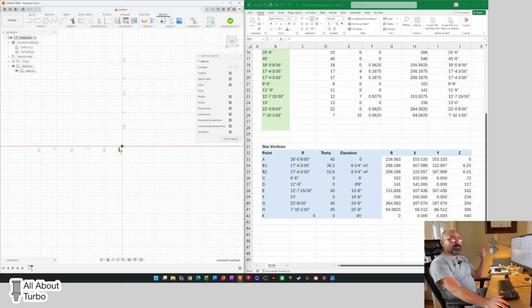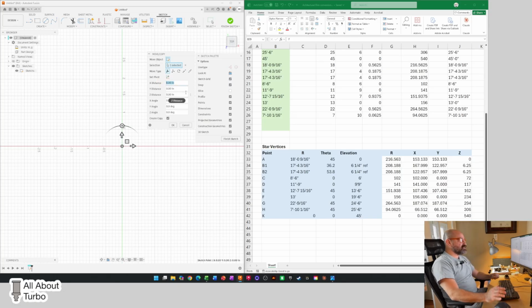But I want to move that point around as I copy it, so I'm going to delete that constraint. So now this point can move. Okay, now I want it to be at origin because this is how my next steps are going to go from here. I double click on that point and it opens this transformation window. I'm going to make copies of this point. So I'm going to say create copy, and here it's very convenient. I can start typing in my X, Y's, and Z's.